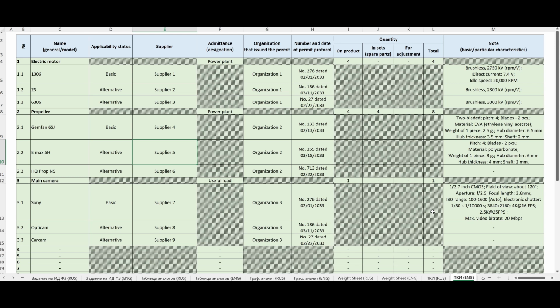The work performed at this stage should not be confused with the formation of the BOM, the bill of material, for the products being developed, i.e. in fact the first estimate of the structure of the unmanned aircraft system being developed, provided that its components are manufactured primarily using prototype technologies: 3D printer, manual locksmith work, stamping and prototype tooling with a small, for example, silicon casting, vacuum infusion, manual laying out and molding of composite parts, etc.